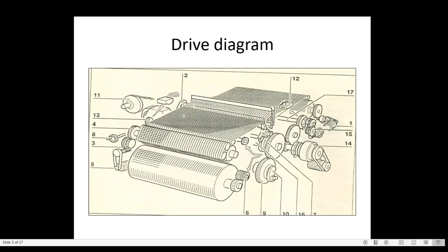On the rear shaft we are having leno devices. So from the main shaft the drive has gone to the sley. Again the drive has gone to the auxiliary shaft to the opposite side, and again to the rapier drive or hand wheel. So rapier drive on the right hand side, and again back side it has gone. So how many shafts are present here? This is the rear driving shaft, main shaft, sley shaft, then auxiliary shaft. Like this the shafts are there.